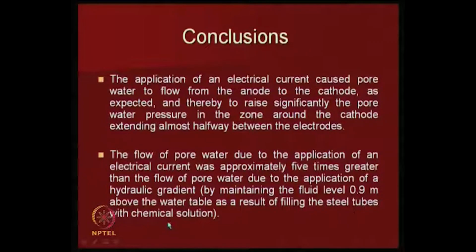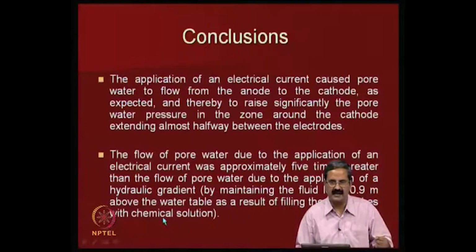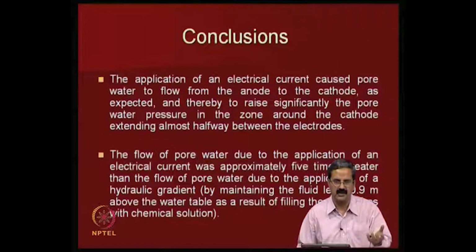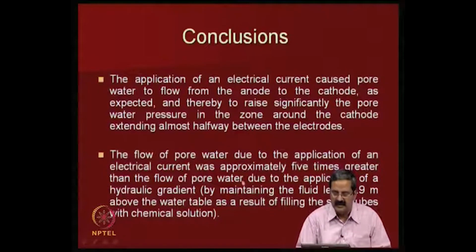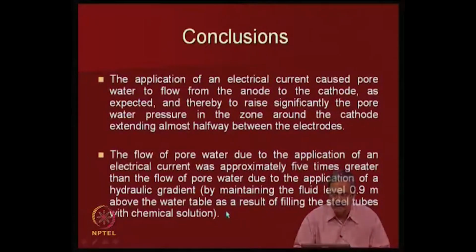So, this is a very important observation, as I just mentioned: you may have electrical gradients, you may have hydraulic gradients, like by gravity alone, or by drainage, or even you can apply vacuum. The other day we studied vacuum consolidation also. You can apply some gradients, but definitely the use of current will significantly change the rate of removal of water. So, this is a very important point. In fact, people have done a lot of field studies on that, and I will show some.